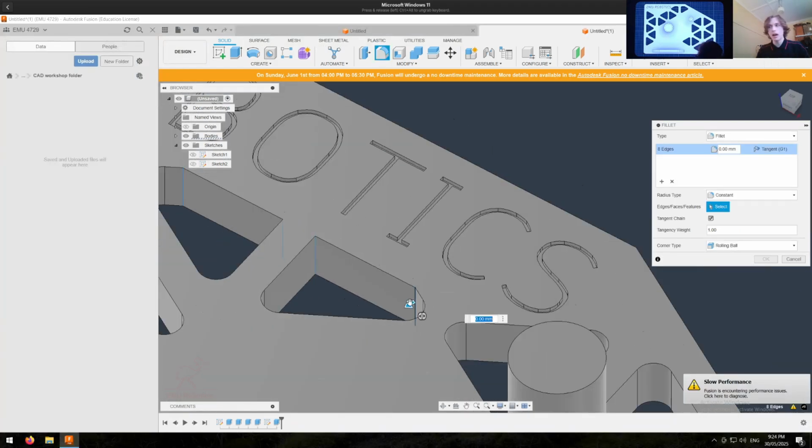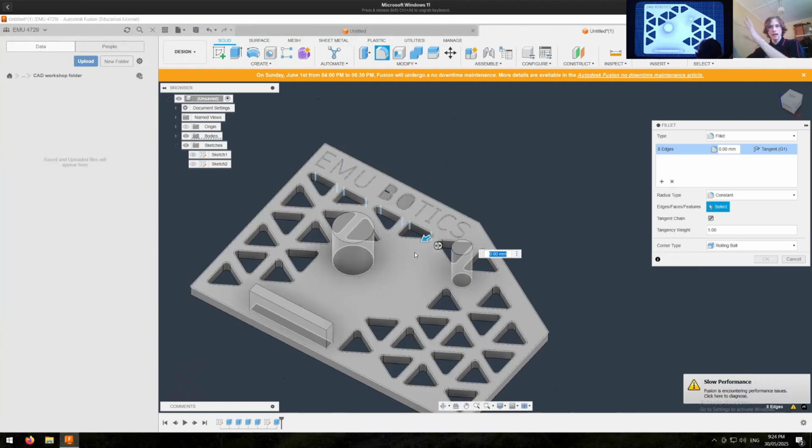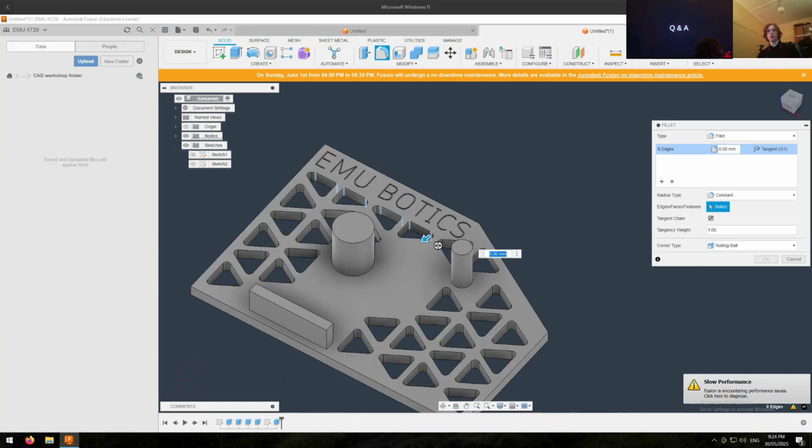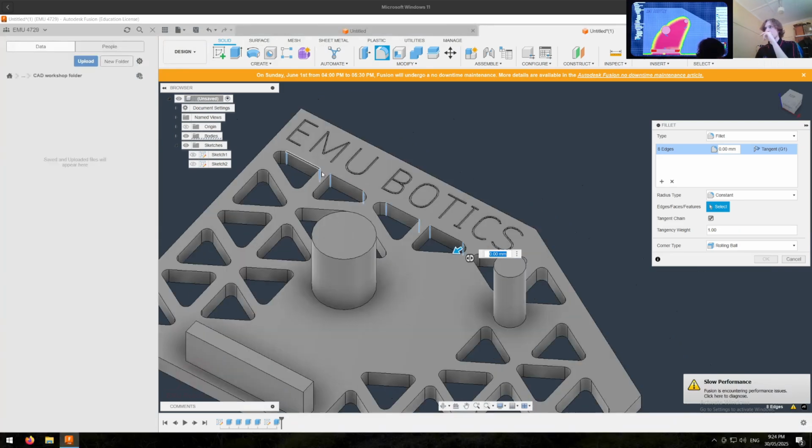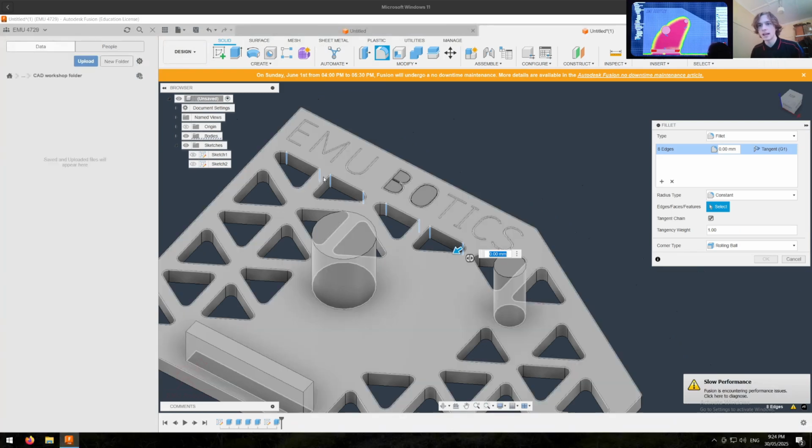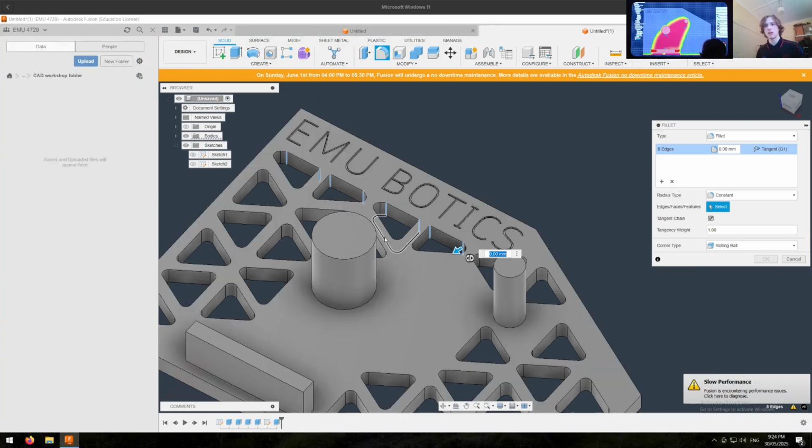Because if any part of this assembly is going to fail, it's going to be that place where we had that sharp corner. You can kind of picture, if we go back to the overlay, all of this red area, you can picture anywhere you have a sharp point on your CAD model. So like these little areas here, those will be red areas. And we don't want red. Red bad. So I'm going to add, let's say, 2 mil fillet. Actually, no, maybe I'll do more than that. 3. Yeah, I think 3 is good.